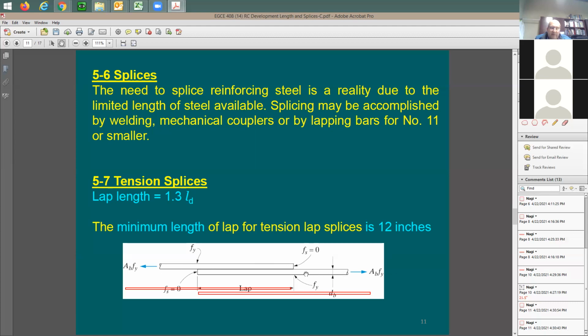It's going through the rebar, and at each little segment of this rebar, you have transfer of this tension from the steel to the surrounding concrete. Concrete is going to be taking this and delivering it back to this rebar. With that, you splice it, which means that you transfer the force from this side to that side without welding these two rebars to each other.